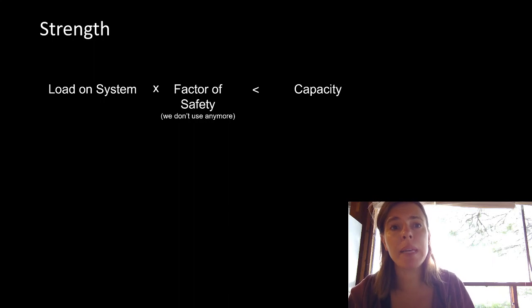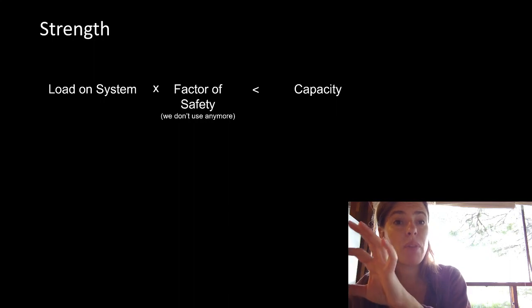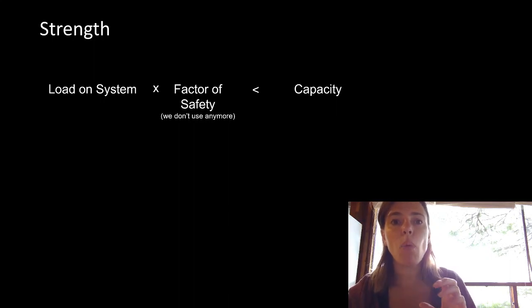Now, the problem is, what if Shannon goes out and eats a turkey dinner? What if the table is a slightly different thickness than we thought? This didn't treat all load types fairly. And in the end, what we do is we break it down. Okay, well, we're designing this for 1 Shannon. Well, Shannon can have some variation. She can put on some weight. Maybe yesterday she went and had a cheeseburger. And maybe what we'll do is we'll design it for Shannon with a buffer and all kinds of cheesy burgers and beers, and put a factor on that. And then we'll say, okay, but the weight of the table could have some slight differences, but we're buying that from a mill, and so we'll factor that as well.